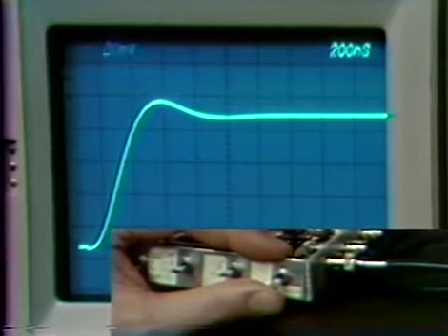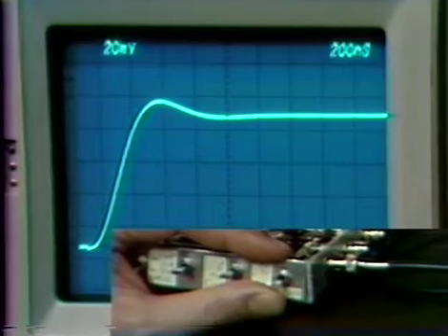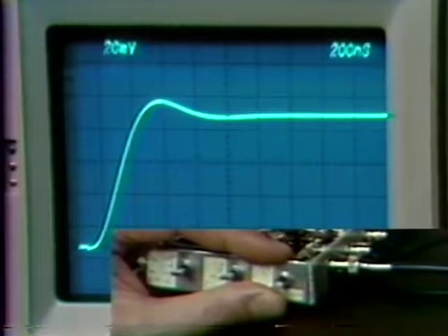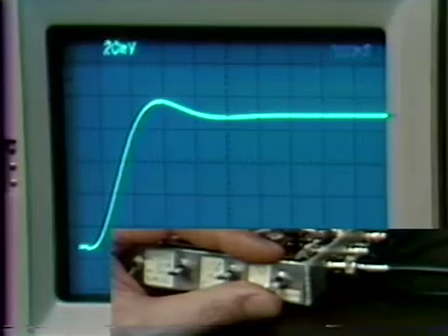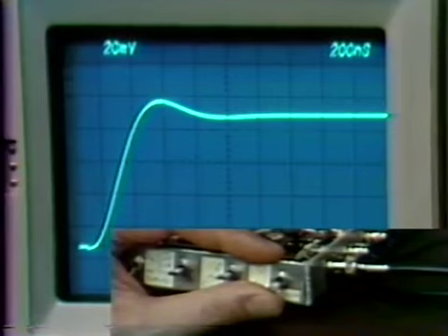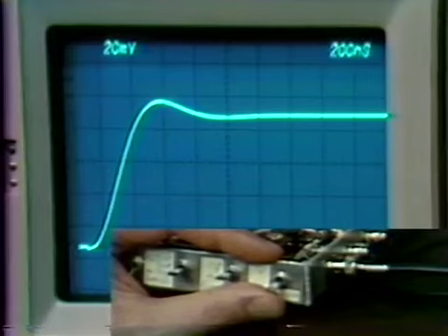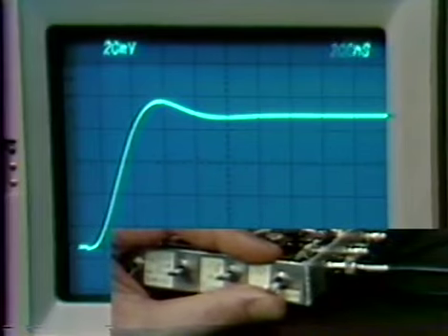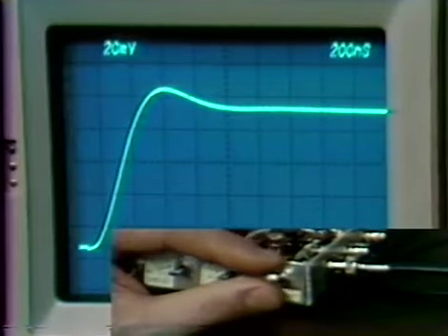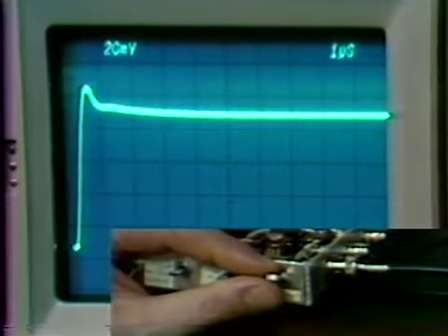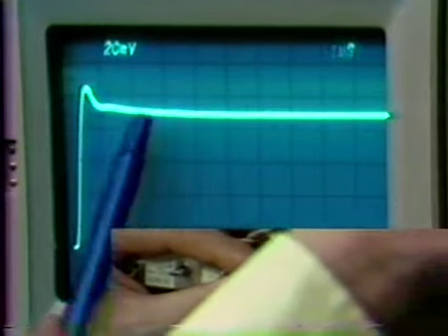You recall that the zero associated with 1 over s squared compensation introduces a long tail to the transient response. If you do a root locus plot for this sort of an amplifier, you find that it includes a relatively low frequency pole-zero doublet, the zero being the zero associated with the two-pole compensation, and the pole being one of the system poles that in a root locus analysis moves close to that zero for large values of A0, F0. That pole-zero doublet gives us a tail with quite a long settling time compared to the basic dynamics of the system. We see that prolonged settling time here.